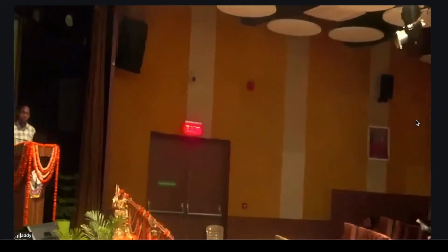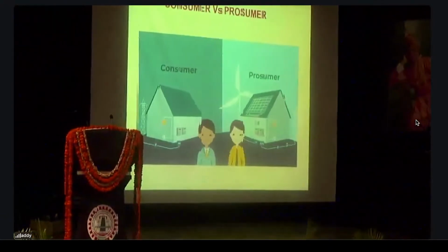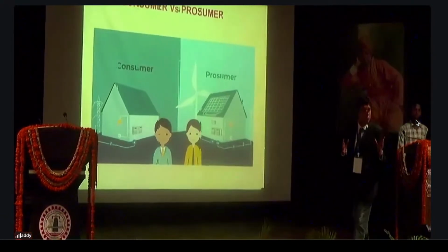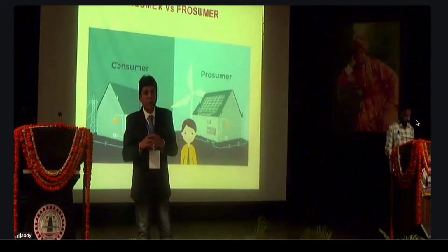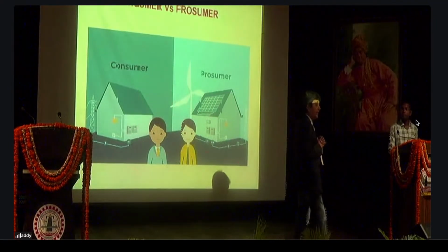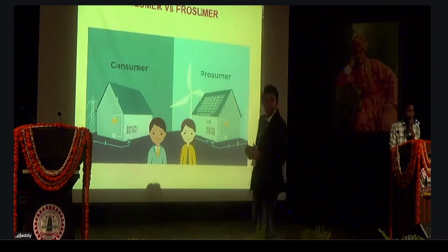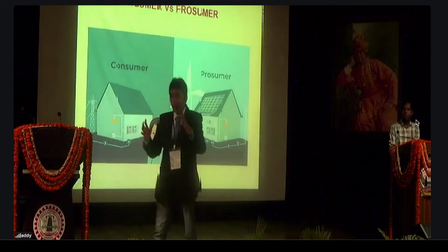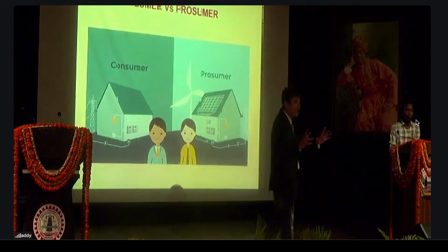The challenges of intermittent power, the challenges of flow of power on both sides, the challenges of insulation coordination, the challenges of protection coordination, and challenges of use of electronics inverters that creates problems of harmonics. When I say harmonics, it has direct link with the power quality. It has direct impact on the power factor of my system. When my power factor deteriorates, there is chances of more heat. When more heat is there, there is chances of fire.